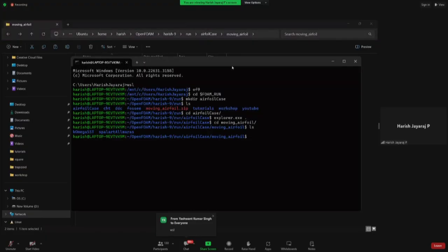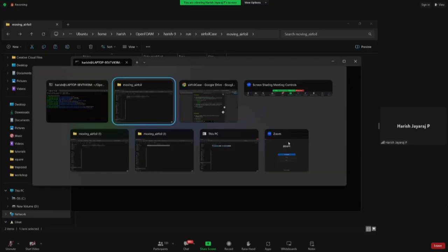To keep up with the PPT, I'm going to do kOmega-SST at RE1E6. But if you want to enter Spalart-Allmaras inside RE1E6 or RE20E3, you can do so using the cd command. It is up to you, but for the tutorial case, I'll be doing kOmega-SST, and inside that, I'll be choosing RE1E6. So once we are inside this directory, everything else from the PPT should work, regardless of whether it is a WSL or Ubuntu machine.